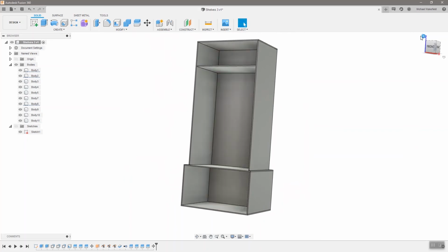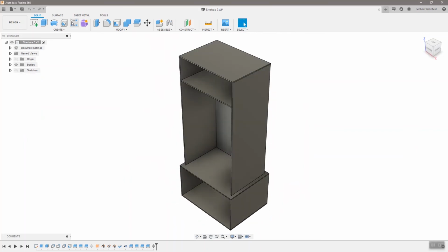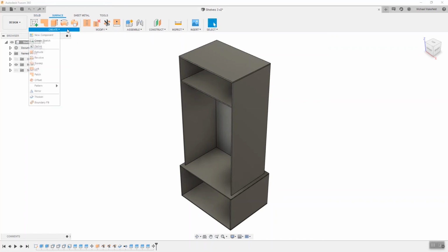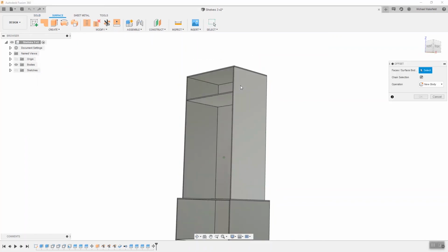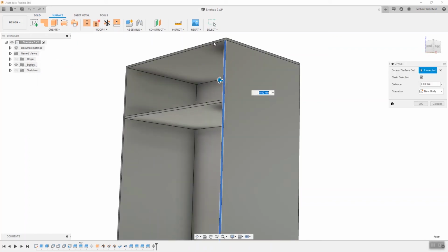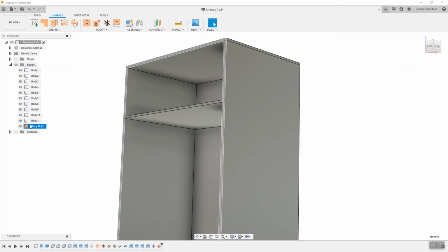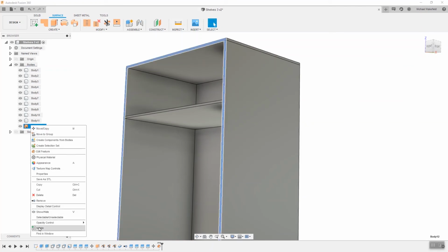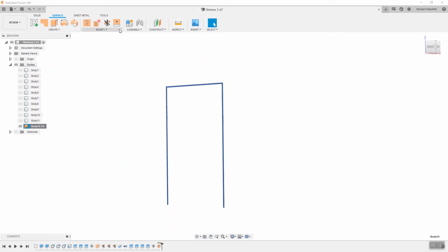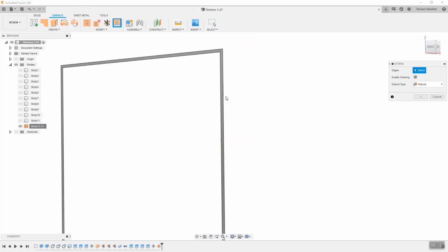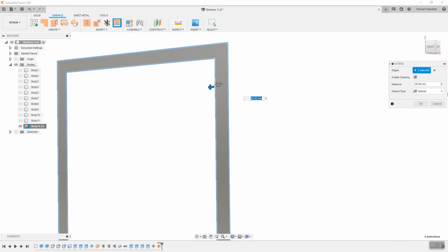The next thing I did was to do something a little bit decorative. Again, I go into the surface functionality and I create an offset surface using these front faces that you can see on the top set of shelves. I do an offset of 0, which doesn't seem very logical until you realize that creates a surface that I can then manipulate individually. I can then use the command extend to extend out the inner and outer edges of this very thin, very small surface.